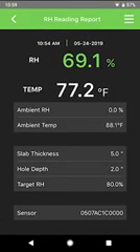The Measurement Details screen provides detailed information about the measurement, such as the sensor serial number used for the measurement, the date and time of the measurement, the RH and temperature, as well as the ambient RH and ambient temperature at the location. The slab thickness, hole depth, and target RH are also specified in the settings. This screen is very similar to the real-time reading screen that is displayed when a new measurement is made.